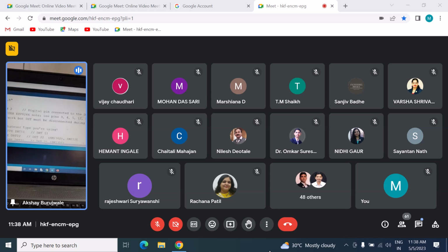So in the code, we see that it is connected with pin number 2. We can change it to whatever pin number they have put here, say pin 5. Most of the time we use pin 2 or 3 for RX and TX. So here I am commenting out the other code and opening DHT11.